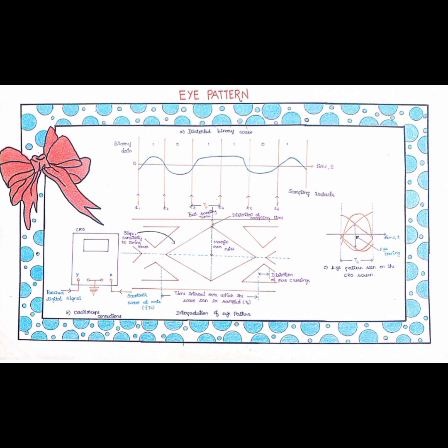Eye pattern analysis also helps in diagnosing problems during system testing. For example, a noisy power supply can introduce extra noise into a signal, visible as a fuzzy eye diagram. Pinpointing these issues early helps avoid expensive troubleshooting later.